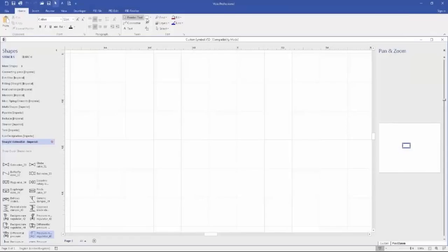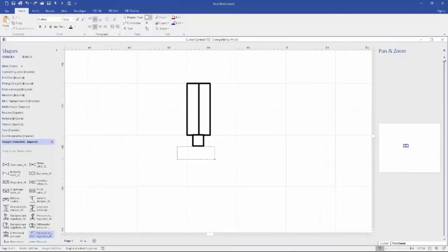Custom symbols. Custom symbol creation is very easy in Visio P&ID. Users can create new symbols for a specific object class using Visio graphics. So let us create a valve symbol using Visio primitives. The create new symbol command allows you to create new symbols for any object class with necessary details like connection points and display attributes. Objects get created in the default database for new symbols, and you can use this command across various projects.